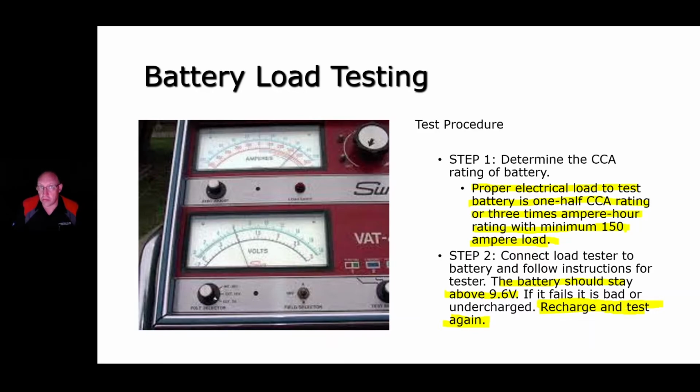The more electrons we move, the hotter things get, the faster things melt. So do not use the alternator to recharge the vehicle. If your battery went dead and you jump-started your car and you got a 5-hour drive, that's another story, right? It's probably going to be charged by the time you get home. The alternator is going to take care of it. Not that you wanted to do that, not that that was the ideal condition, but if you got a 5-minute drive across town or a 10-minute drive across town, when you get home, get a battery charger out and put it on your car for a couple of hours and charge that battery back up, because the alternator didn't do it going across town, okay?